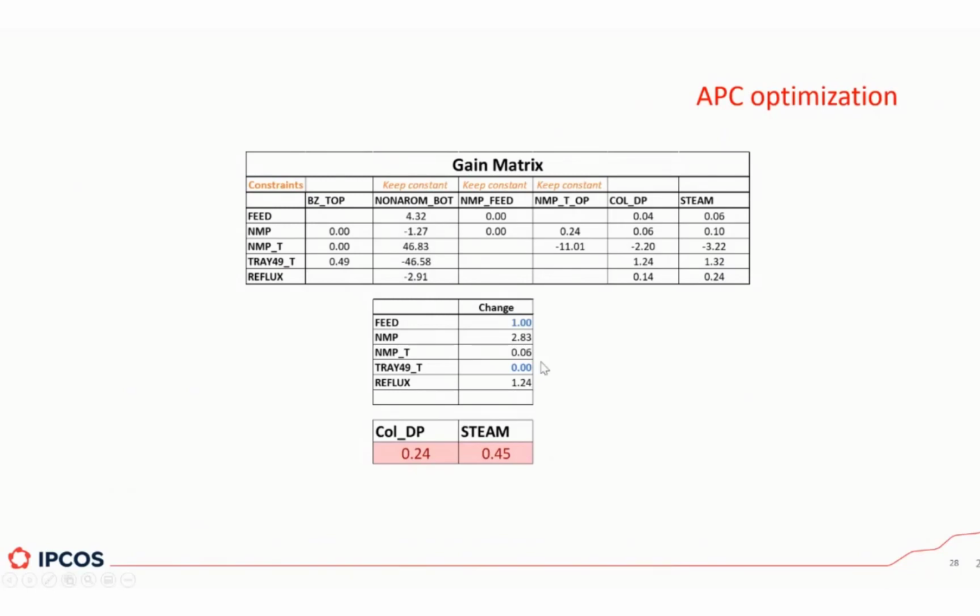But then the interesting thing comes here. If you noticed, I purposely put 0 change in that tray temperature that we have been talking about the whole time, the one that uses the steam. So basically, the amount of steam changes, yes, but in this case in particular, it's not changing because you are changing the tray temperature. It changes because of some other things.